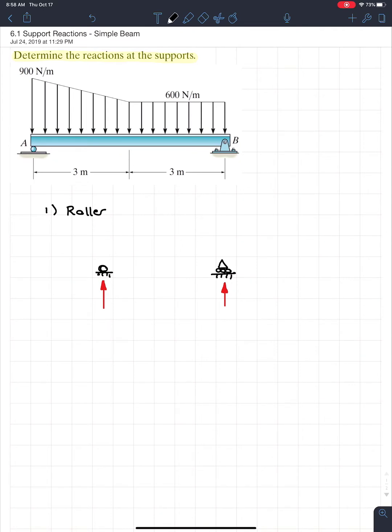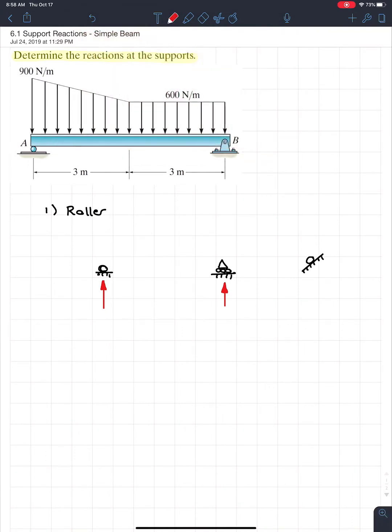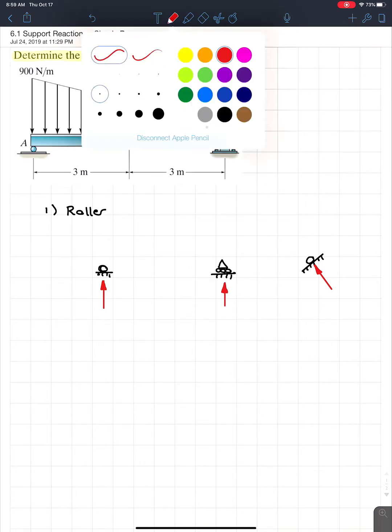So if I have a roller that's on a surface like this, the support it's going to receive will be perpendicular, so it's actually going to be at an angle like this. And I have a video for that later. Don't worry about it. We're going to cover that, because although it's a very rare case to see, it's definitely one professors like to test you with. So that's a good one to know. So again, one support reaction, really nice, really, really easy.